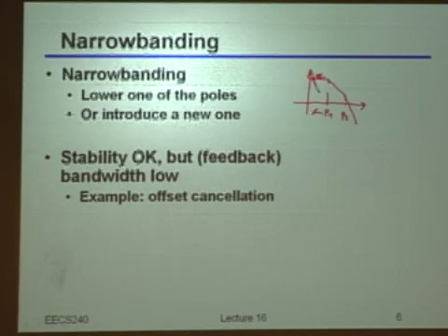So my pole now shifts here, 20 dB per decade roll off, and then I would hit the omega axis much earlier than before, and then I will start with my minus 40 degree later. So the point is, there I'm going to be stable and I'm going to have the phase margin that I wanted, right? But at what cost, right?